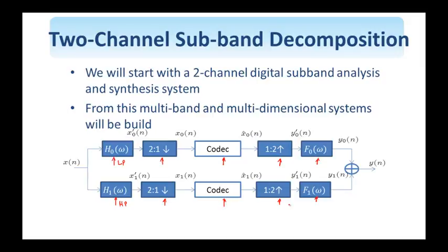Conceptually, the upsampling filters are undoing what the downsampling filter did, you might say, and there is a lot of work on how to design these filters, H0, H1, F0, F1, so that in the absence of compression, I have perfect reconstruction. We don't have perfect filters. If you implement them in the spatial domain, they have a pass band, a transition band, and a stop band. And there are, for example, the quadrature mirror filters that give you perfect reconstruction. It's a topic that has seen a lot of activity in signal processing, and there are quite a lot of results that one can utilize.